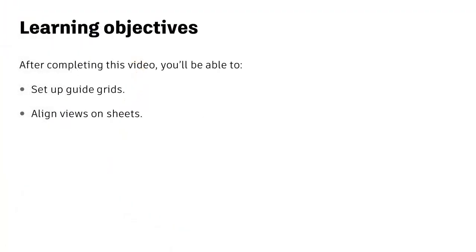In this video, you will see how to set up guide grids and apply them to sheet views. And you will also see how to align views on sheets using the guide grid.